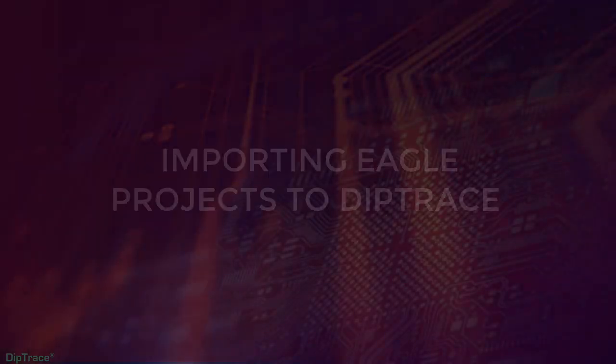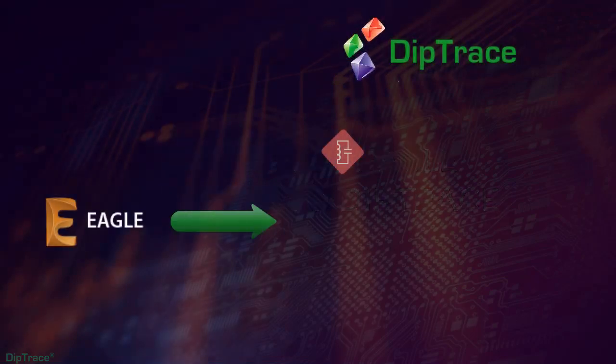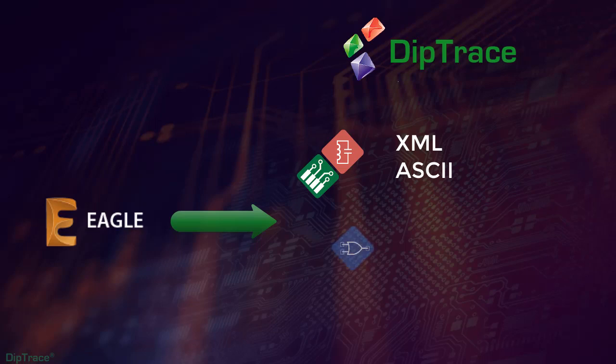This video is going to cover migration of projects designed in Eagle to DipTrace. DipTrace can import Eagle schematics and boards in XML or DipTrace ASCII formats, and libraries in XML and script formats. In every module of the software, the procedure is essentially the same, but let's go through all of them.